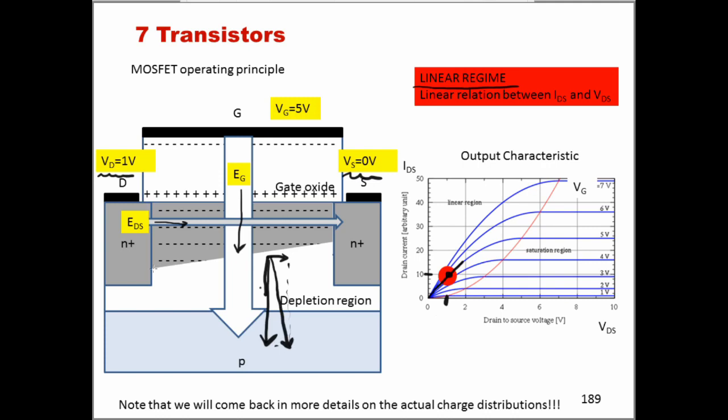And so we see that the sea of electrons that form the inversion region, the channel of the transistor effectively, modify their spatial arrangement according to the direction of the total electric field.